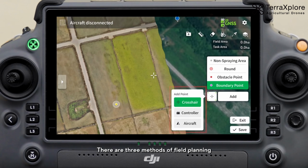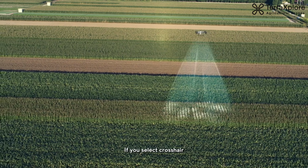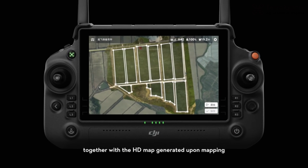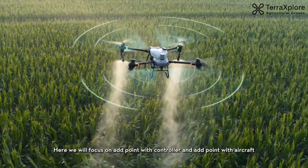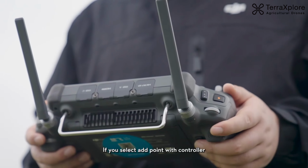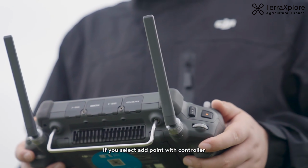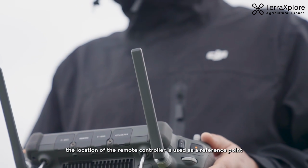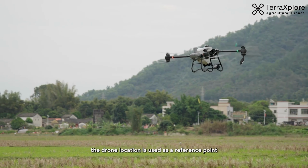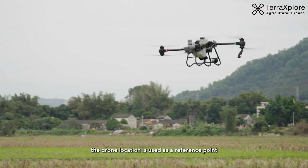There are three methods of field planning: crosshair on the map, add point with controller, and add point with aircraft. If you select crosshair, we recommend that you use it together with the HD map generated upon mapping. Here, we will focus on add point with controller and add point with aircraft. If you select add point with controller, the location of the remote controller is used as a reference point. If you select add point with aircraft, the drone location is used as a reference point.